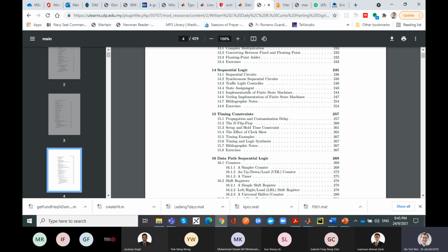So what do I mean by that? When you have a digital circuit, there are circuits or logic whose sole purpose is to figure out the current mode of operation of your circuit, right? Because you have a very flexible digital circuit, you can do a lot of things. You can do a multiplication, an addition, a shift, many computation operations. So you have to decide, let's say I give you a set of data, which operation you apply. That is the control path. And the data path would be, what do you do with the data? So there are generally two parts to a digital logic circuit, the control path and the data path.